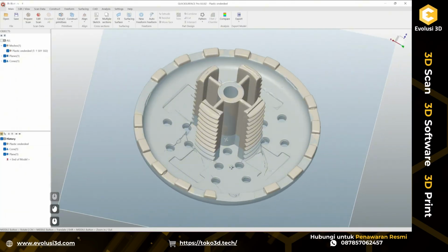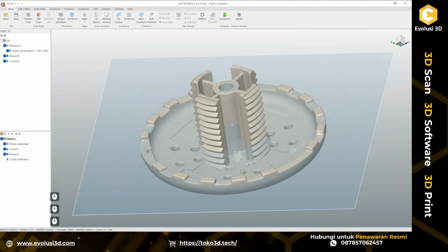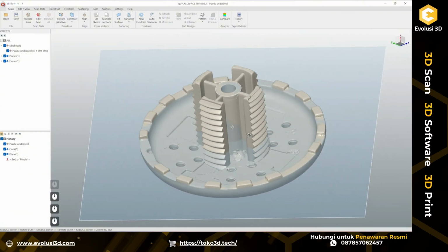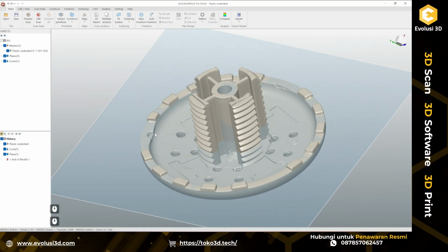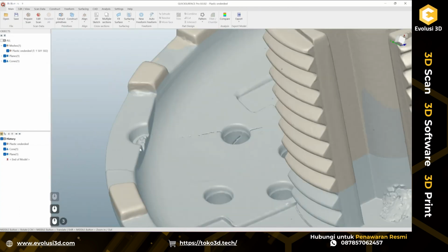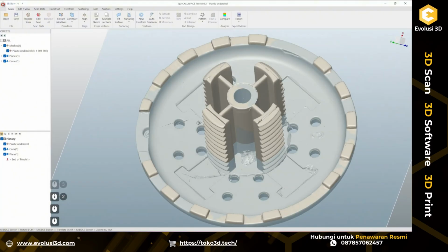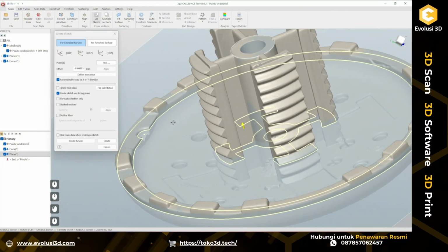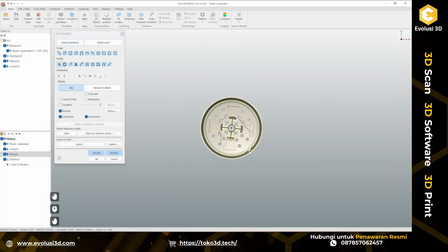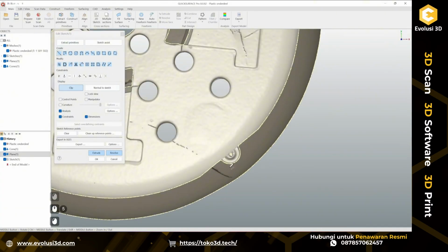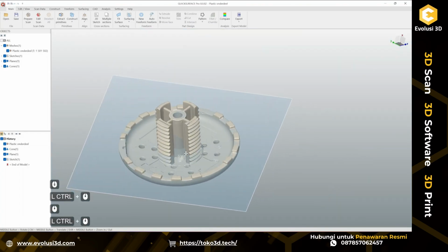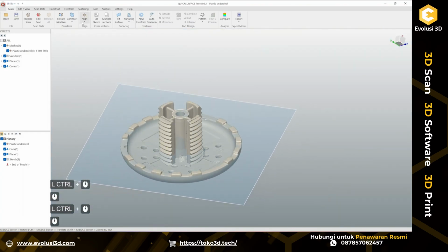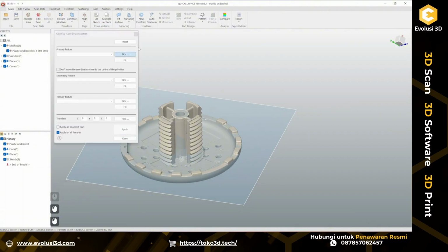So let's create this one, and as a third feature, probably I could use this straight line here to define direction. So let's fit one entity there by creating a cross-section sketch and fitting a line here. Okay, so we have done this, and let's align this by coordinate system.